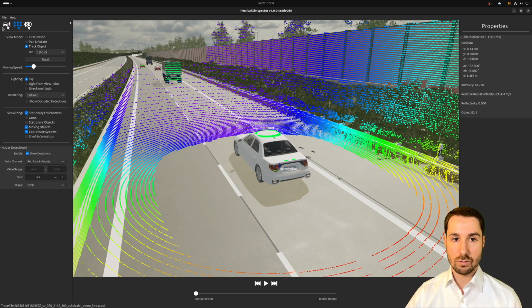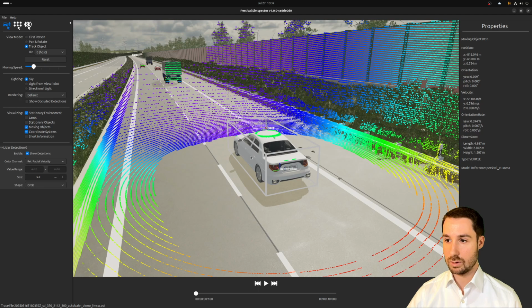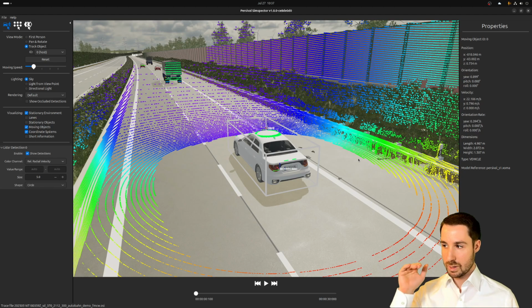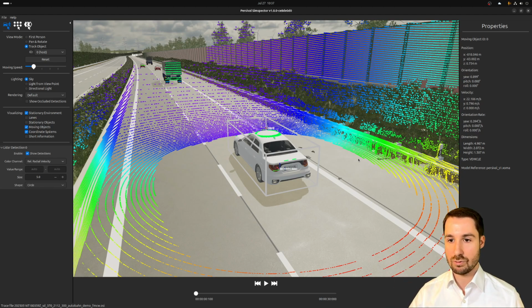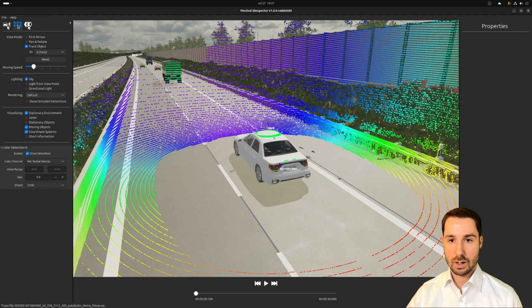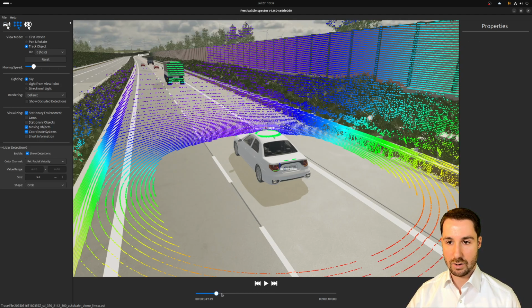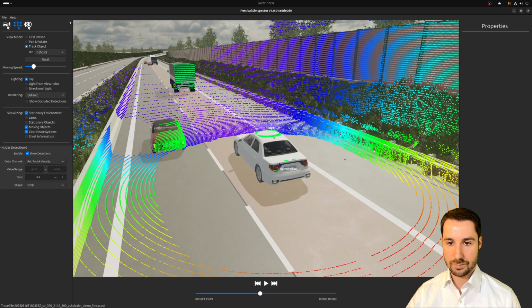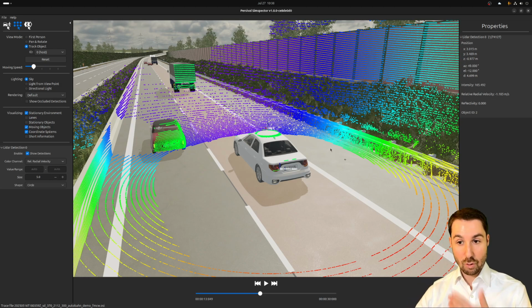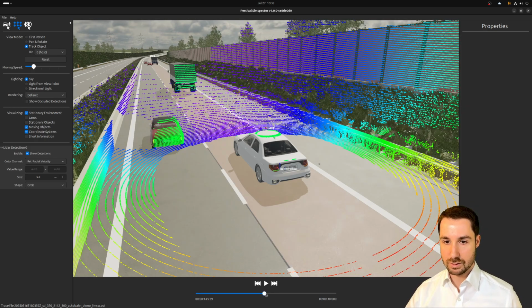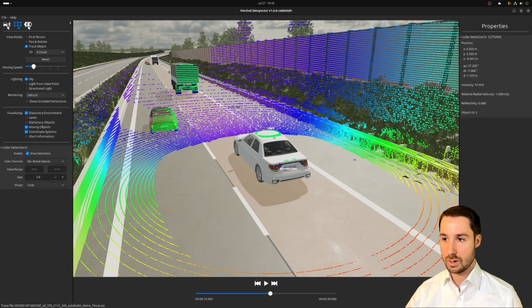And that's very close to the ego velocity. If I go here and select the ego vehicle, you will see the velocity here, and that's actually 22 meters per second. There's a little bit of a deviation because we're not going straight in front, so slightly angled down, so the radial velocity component is a little bit less, but you can see that here. And if I have a different car going by, like this one, I can also go here and see the radial velocity. It's close to the ego vehicle speed, a little bit faster. So it's going further away. And you can see that here with this negative radial velocity.